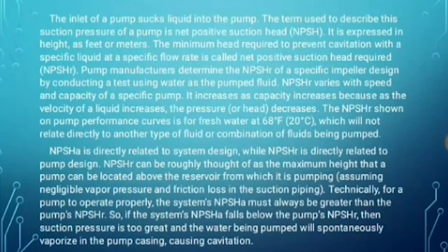Net positive suction head (NPSH) is the term used for the inlet of a pump where it sucks liquid into the pump, expressed in height, feet or meters. The minimum head required to prevent cavitation with a specific liquid at a specific flow rate is called net positive suction head required (NPSHR). NPSHR is gathered through tests, varying with the speed and capacity of the pump.